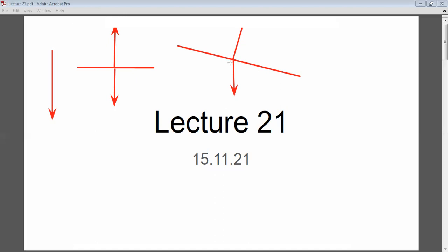Same way, if I elongate the spring, it will not be happy in that position. Once I remove my hand, it will go back to the relaxed shape. So also in this case, by Hooke's law, tension is equal to k times delta L, where delta L in this case is the elongation. That's the magnitude, and the direction of the tension force is always along the spring, or along the string.